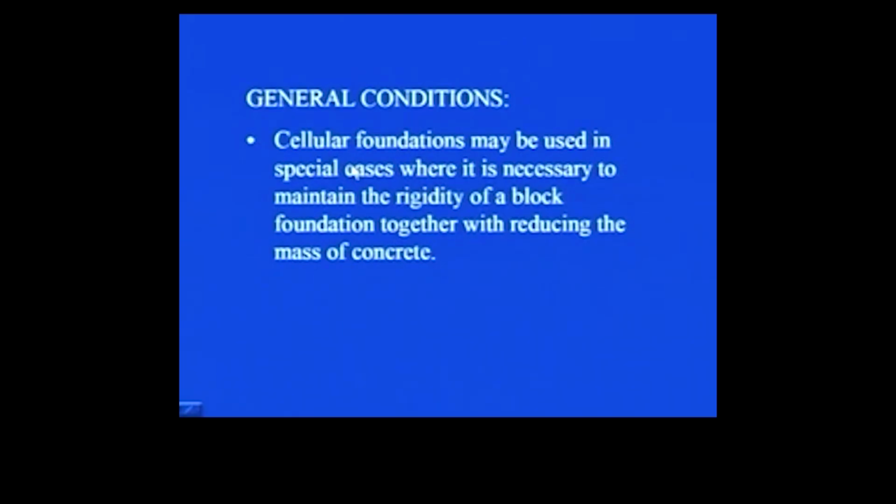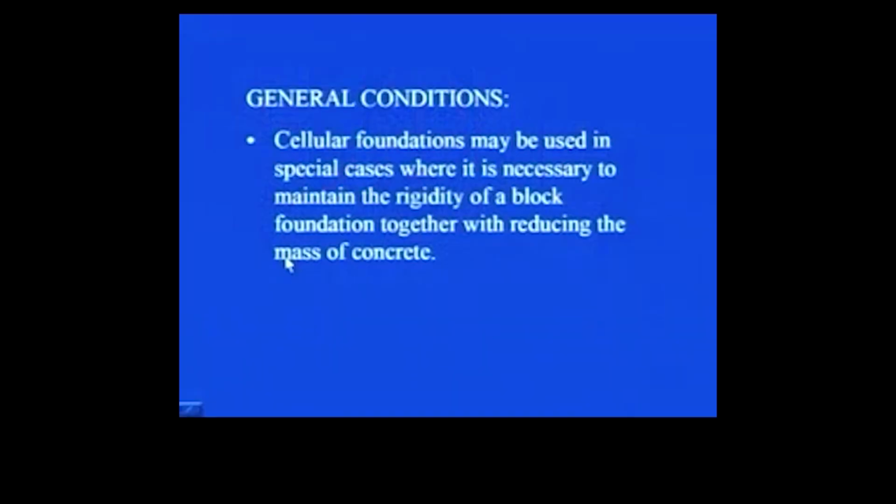Wherever the block foundation cannot be put, or the weight of the block foundation, the mass of the concrete used in its construction, is quite high and not permissible, or when the conditions are not favorable as far as the block foundation construction is concerned, there you can go for the cellular foundation.